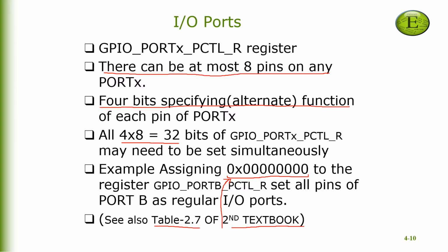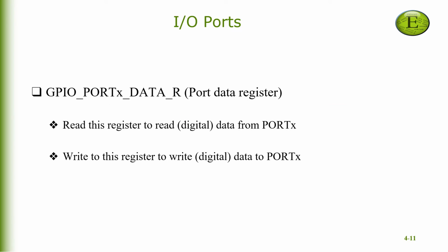And finally, we have the port data register. If we want to read data into the microcontroller from port X, then we are going to read this register. Conversely, if we wish to output data to the port, we write this register. That will send data to port X.